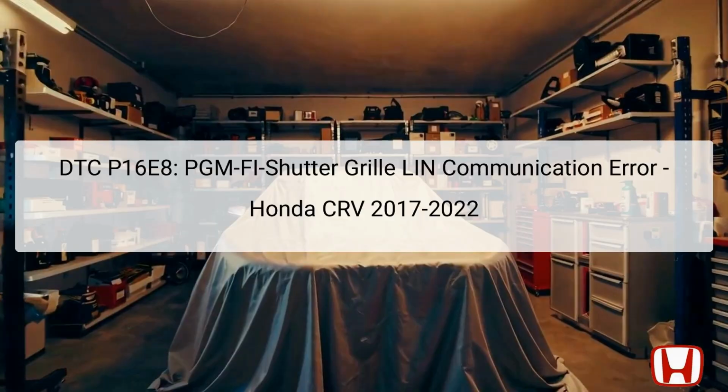The error code P16E8 pertains to a communication error between the Powertrain Control Module and the Shutter Grille System in the Honda CRV models from 2017 to 2022. This communication failure can impede the operation of the grille, which plays a crucial role in managing the vehicle's engine temperature and aerodynamics. Located at the front of the vehicle, the shutter grille is controlled by the Engine Control Unit, ECU. A functional communication pathway is vital for the correct activation and regulation of this system.